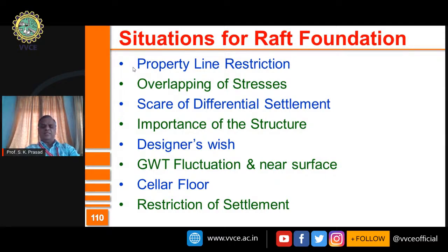Another important reason is provision of cellar floor. For various reasons, designer may have to provide a cellar floor. Maybe they want to increase the number of floors. Maybe height is restricted, therefore, they want a few cellar floors for car parking or so. Under that situation also, the designer goes for raft foundation.